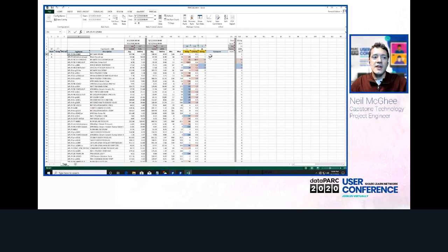Using 6 sigma as our standard limits, we have the limit set to 3 sigma, and we can see the highlighted limit violations. These two statistics may seem redundant, with SD change always being the obvious choice over percent change, but percent change can still be useful if our baseline was only a short period of time where the standard deviations of the hourly average may not be truly meaningful.